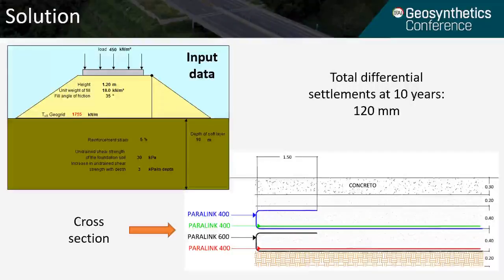The total tensile strength of geogrids required to support the load of the granular material itself and the overload of the minerals dumped in the storage area of the port, for a total uniform load of more than 9,000 pounds per square foot, was calculated using the design method for embankments over weak foundations included in the British Standard BS 8006-2010.